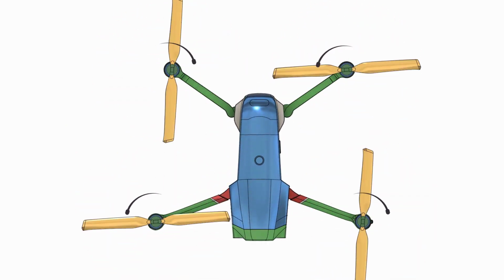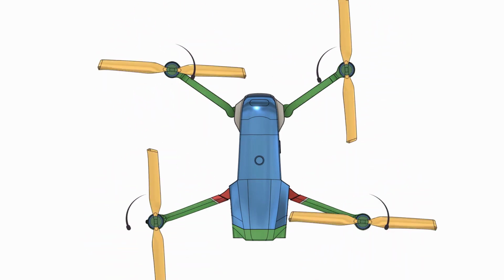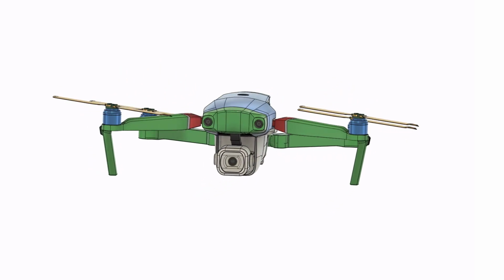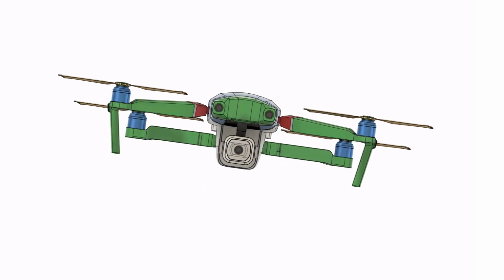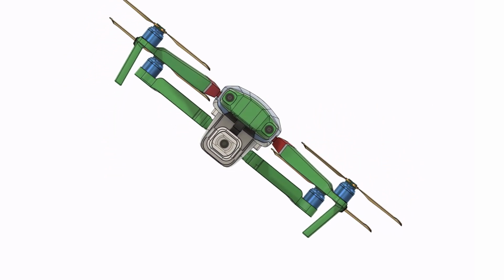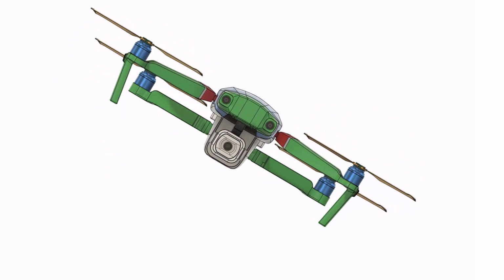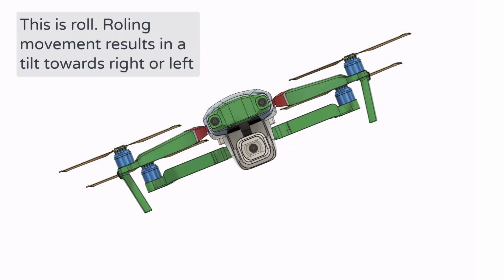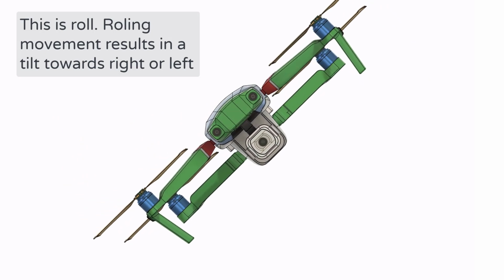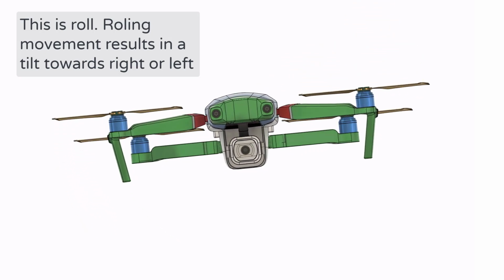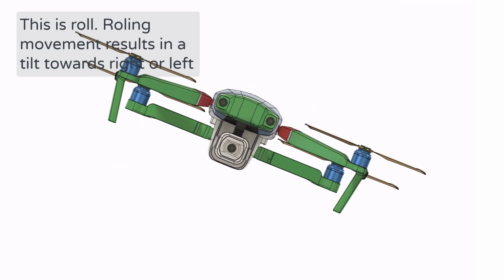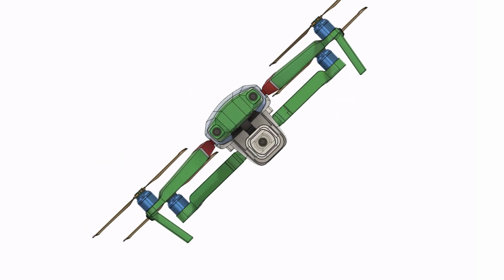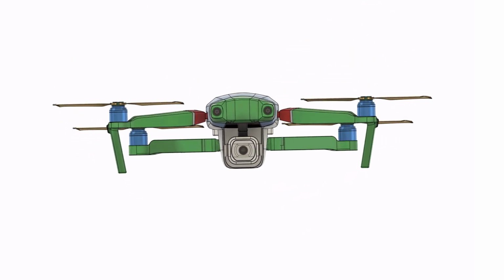In the case of a quadcopter, the term 6 degrees of freedom breaks down as follows, and the movements are exactly the same as described before. However, you're watching this quadcopter from the front. It also has 3 rotational movements and 3 translational movements. The 3 rotational movements involve changing the orientation of the drone. These include rotation around the x-axis, roll. This movement occurs along the longitudinal axis. When a quadcopter rolls, one set of wings moves upward while the other moves downward, resulting in a tilt.